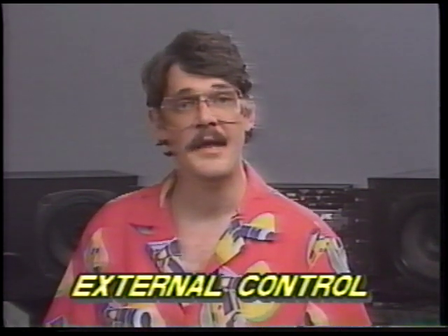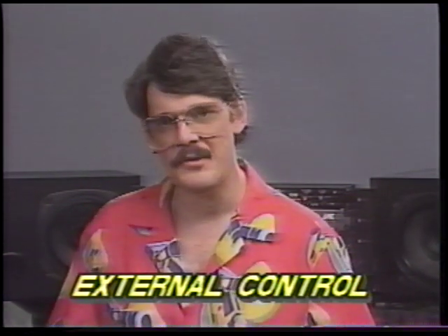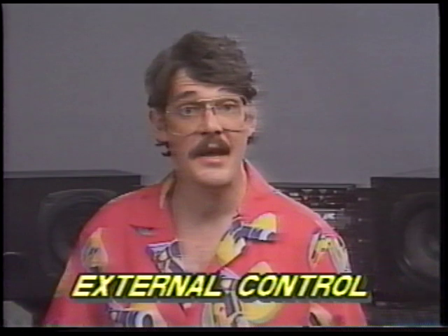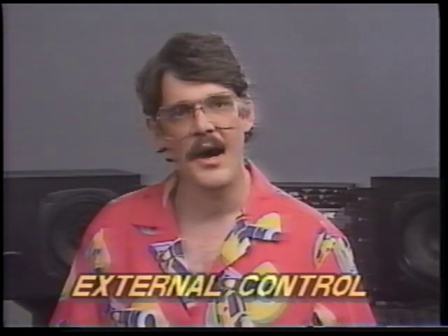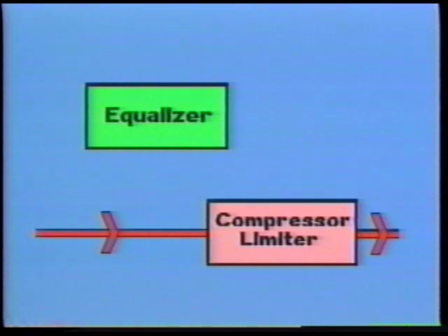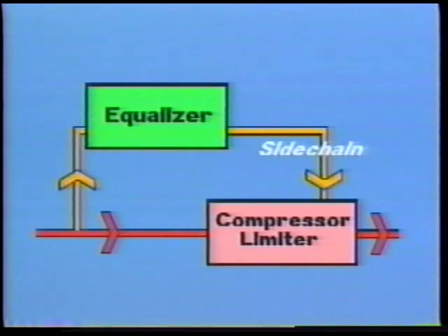An access patch point between the threshold detector and the variable gain amplifier provides opportunities to use the compressor limiter in many other ways. For instance, a few compressor limiters have elaborate built-in parametric equalizers. This provides frequency-dependent variable gain control. But a similar effect can be attained by placing an equalizer in the side chain of the threshold detector. This allows the compressor limiter to become more or less sensitive to certain frequency ranges.